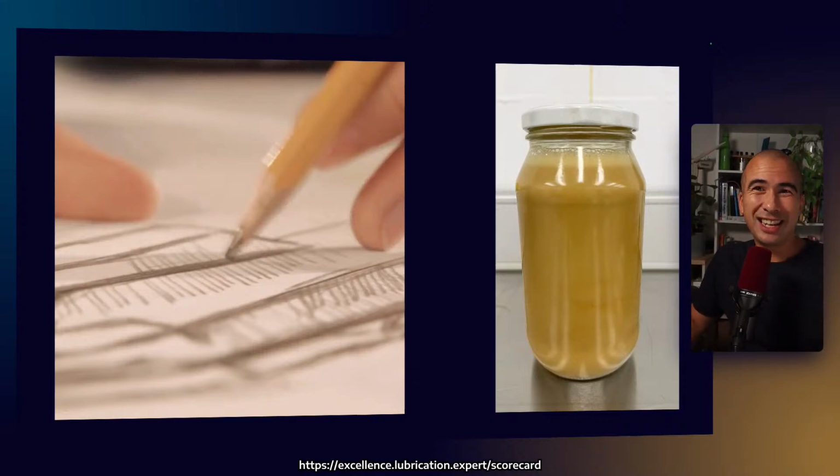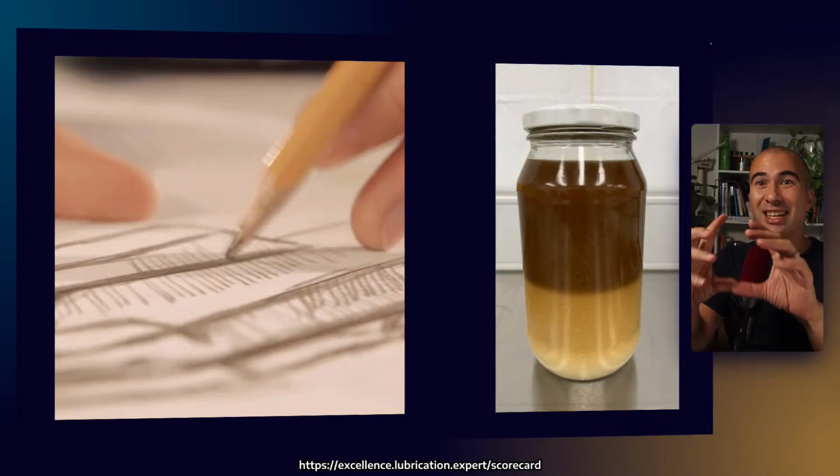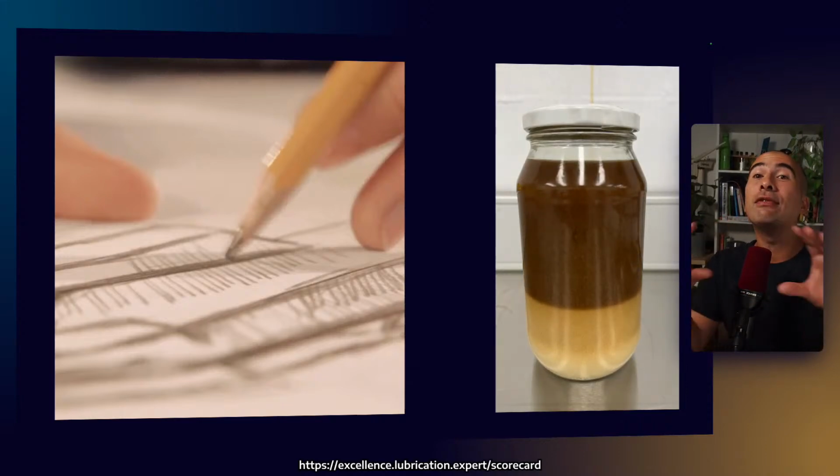Now, solid lubricants tend to be used in greases, not so much in liquid lubricants, because this is what happens if you put them in liquid lubricants. Over time, they do tend to separate out. So this is a time lapse, only over a period of about an hour. That is a PTFE fortified gear oil, and you can see that there is considerable separation even just in that single hour.